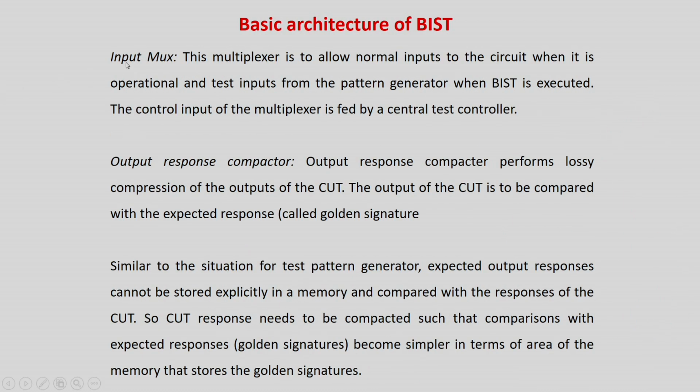Input mux, as I already told you, tells that when the system is operating in normal operation, the primary input should come in. In case of test, the patterns from the hardware pattern generator should come in.